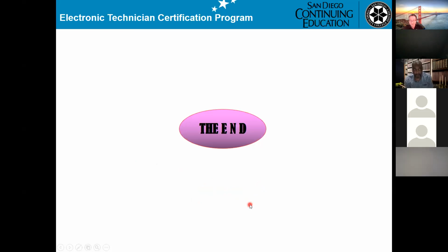So in this circuitry, for instance, we're looking at most likely either the diodes or the capacitors, maybe the voltage regulator itself. Those could be the three types that could be problematic. Next week when we go to troubleshooting, this circuitry will be more detailed, with step-by-step training to organize your brain for how to isolate and troubleshoot. One time, 3 times, 10 times, 100 times, then you know what to do.